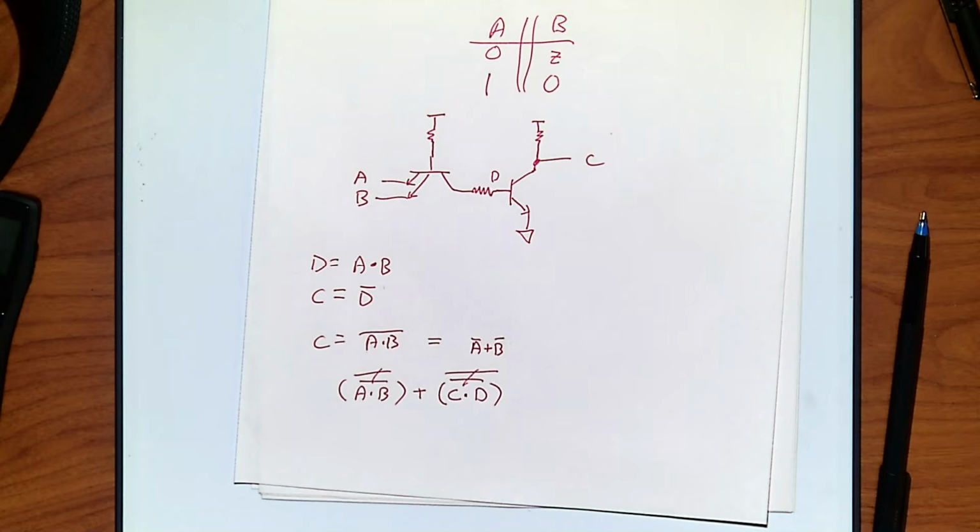So the other universal gate was the NOR gate, which turns out to be the other one, the product of sums. And you can just show that it is also, by De Morgan, the exact equivalent of it. So it's an easy way to show. You can literally build anything out of these if you want, just two layers of either NAND or NOR.